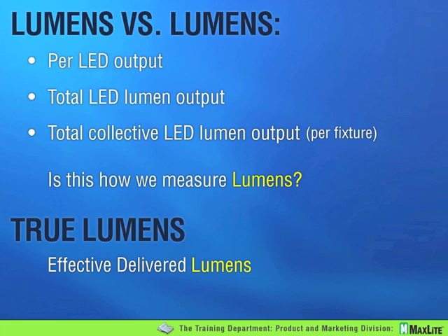And what they're doing, and what many are doing out there, and you have to be very careful, is they are taking, I'll use simple math again, 1 watt chips, 100 lumens each. That's 1,000 lumens when I put 10 of them in a fixture. So they put 10 of them in a fixture, and then they tell you the lumens of that fixture is 1,000 lumens.